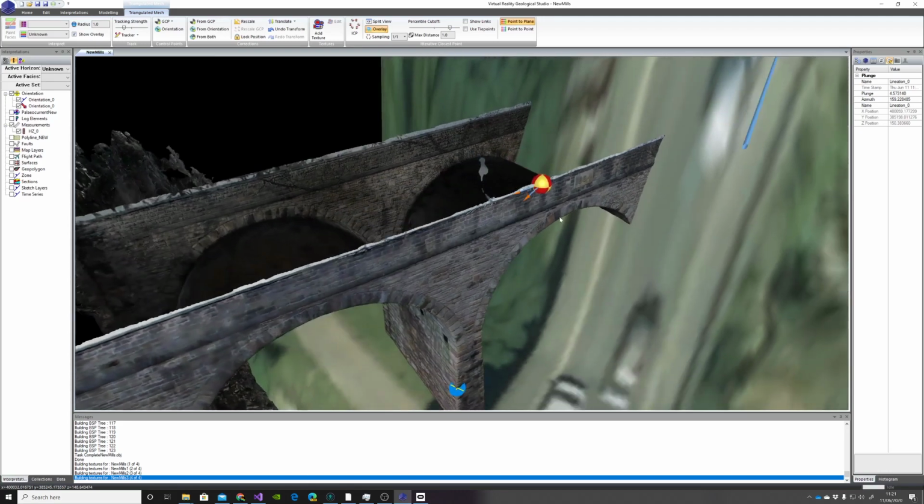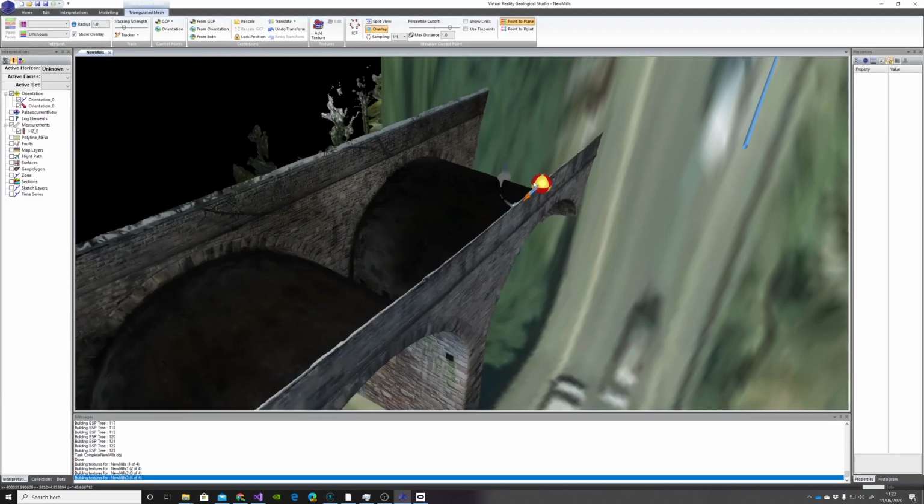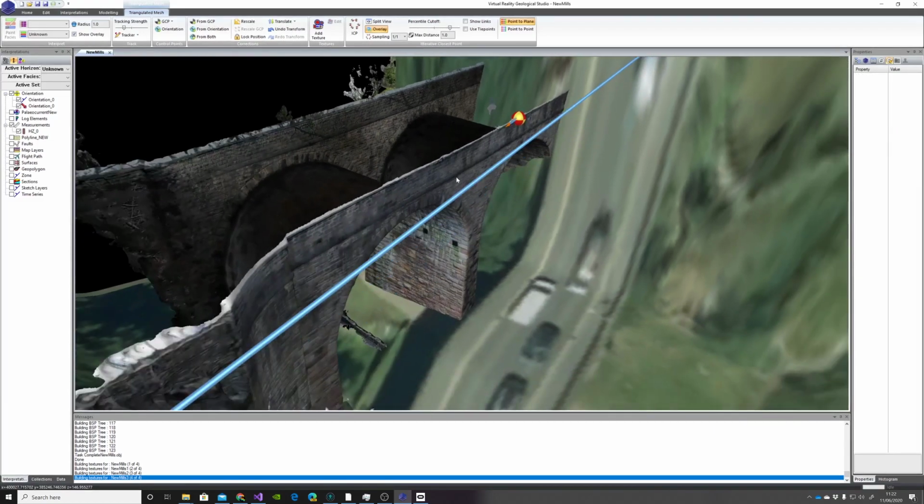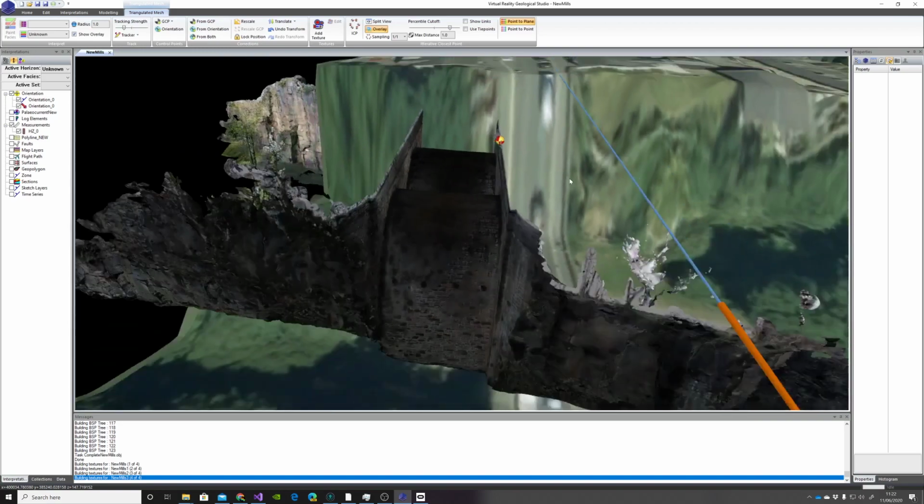And we've now got another control point that this time has two vectors, one that shows the current orientation of our control vector and the target orientation of the control vector. From corrections in our extended mesh menu, I'll use from orientation for the correction. And there you can see it's now changed so those orientations match up.